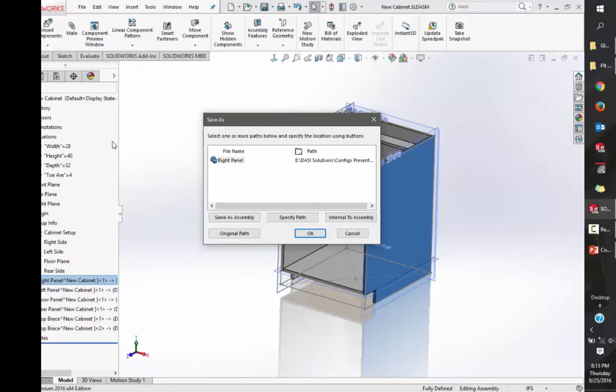When you send it to your customer, you have to send the original plus the Save As? No, they are not connected together. There is no link between the new Save As and the old original one. So no, you can just send them the new data. This actually works out a little bit better too, because if they have SOLIDWORKS, I only have to send them a single file. I don't have to make sure I do the Pack and Go.